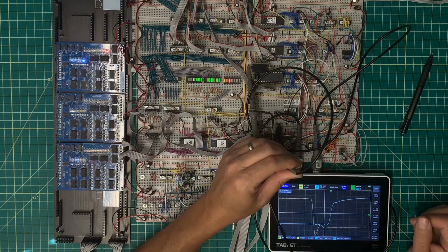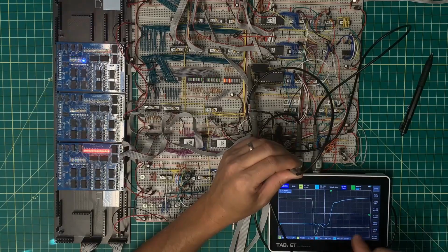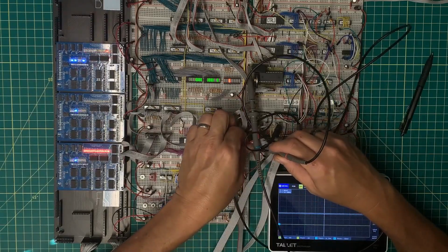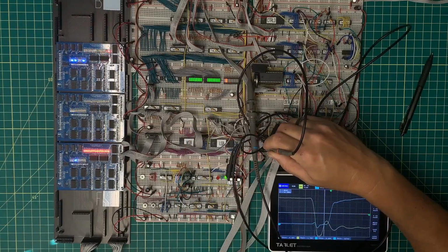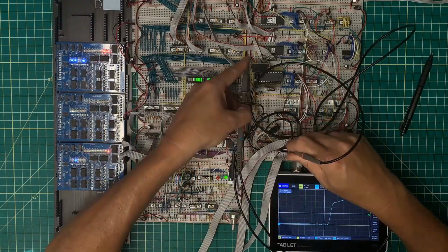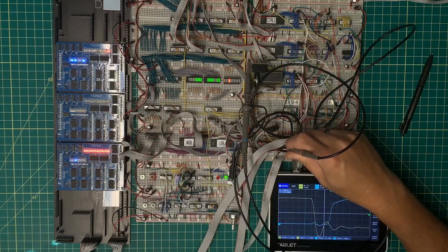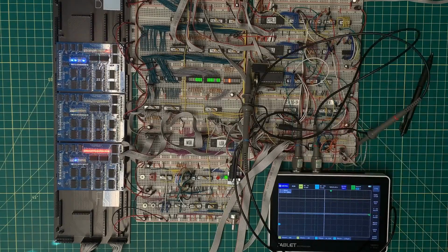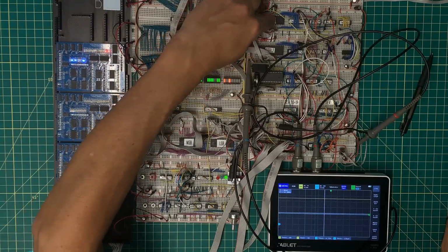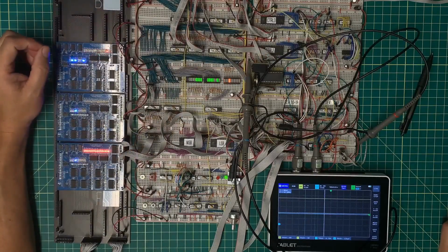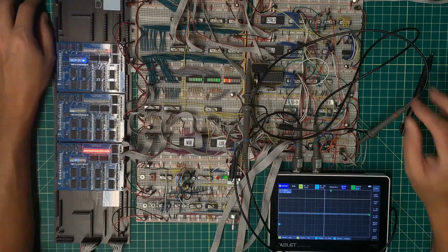I'm expecting that to happen congruent with the falling edge of the clock, but I've got a 150 nanosecond delay. What do we have on the program counter? A similar delay. And R1, about 130 nanoseconds-ish. I guess the question now is, can I shore that up? All three of those AND latch signals are built into control ROM 3, which is here. Those are bits 7, 6, and 5, so the three most significant bits here.